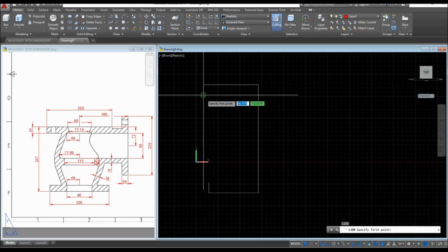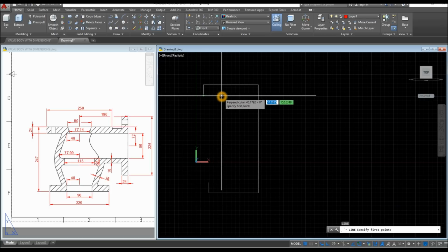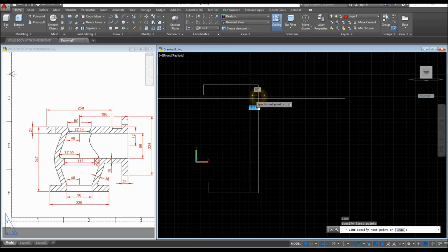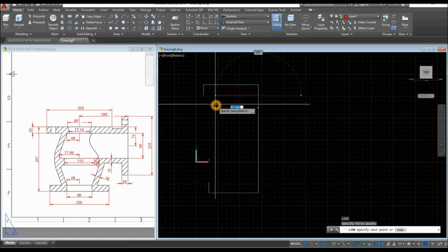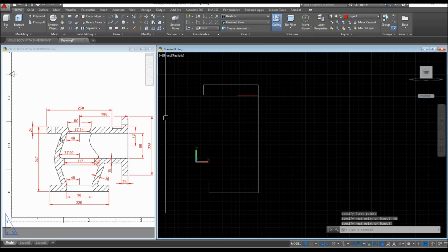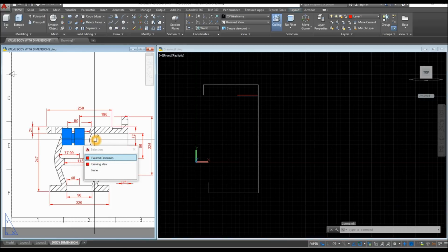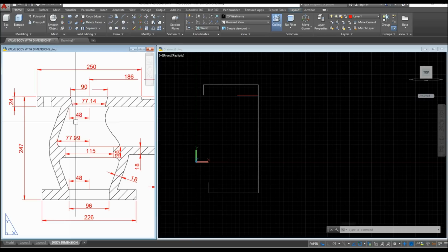So just hover over, don't click, from the endpoint, and move your cursor to the right, and you can see that green dashed line. Just follow that and snap that X and go back to the left and enter 48 units, which is this one here. Because I'm gonna do a 3-point arc, and I need this corner and this corner.